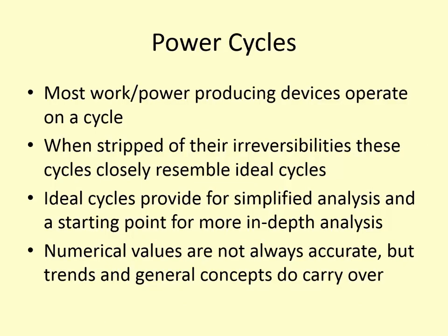Okay, so when we talk about power cycles, we've talked about cycles previously and how we desire to have maybe a net power output. And primarily we've been focusing on these thermodynamic cycles that involve like steam as a working fluid in a power plant or some other similar situation. But today we're going to be talking a lot about power cycles that don't involve a liquid as a working fluid, but involve a gas. So usually a combination of gas and air, and there are certain assumptions that we can make when we're dealing with these cycles in order to make them easier to analyze.